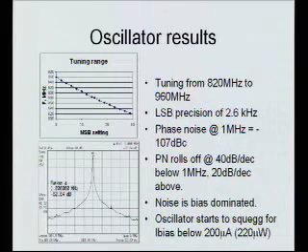But sometimes instead of just turning off, they turn off and wake up and turn off and wake up, and give you this awful AM modulated disaster. That's what this oscillator does if you give it too little power. So it's very easy to detect when it happens. You can put just a little peak detector on there and you know what's going on. So it's easy to avoid, but it's an interesting aspect of the oscillator. This one doesn't just die. It kind of screams a lot first.